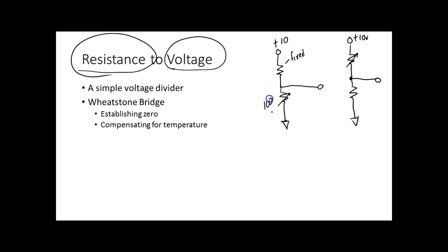Now let's say I have this hooked up to 100 ohms, and this is 100 ohms. That's 5 volts. Then right now I would have 5 volts. Everybody understand that? But what if I come over here and hook this up to a 100 ohm resistor? Well, this is not seen as 100 ohms, even though that's what my sensor's giving me. It's seen as 50 ohms. So my output voltage is now wrong, because of the loading effect. But if I made this 10 megohms, and that was 100 ohms, then the loading effect would be so small it would be negligible. When we deal with these voltage dividers, we have to deal with what we call a loading effect, which means the actual voltage you get depends on what you put it into.